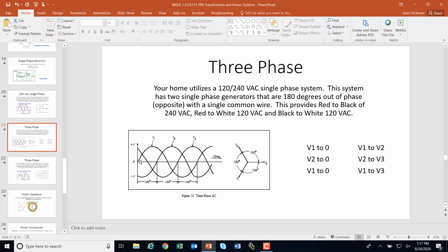So you've got voltage 1. This one starts rolling up and increasing, but then this one is 120 degrees apart, so this doesn't get to 0. When this one gets to 0, this one has already reached the peak and started to come back down. And when the next one, voltage 3, gets to 0, then voltage 1 is coming down and voltage 3 is starting to come down. So these are all 120 degrees apart the way that they're generated.